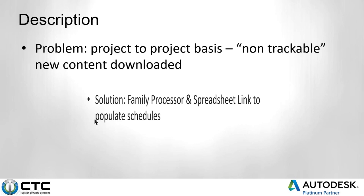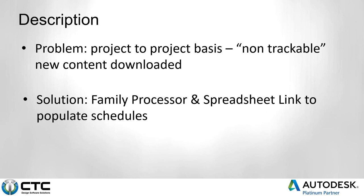So the solution, like I was previously mentioning, was Family Processor and Spreadsheet Link to populate those schedules. You'll see shortly that not only are we pushing additional parameters to a family, but we're actually exporting those same parameters to a spreadsheet. So there's probably an electrical engineer on the other side of the building who may have a minimal presence in Revit. One of those solutions involves sending them an Excel file so that they can make edits to the Revit model without actually being in Revit.